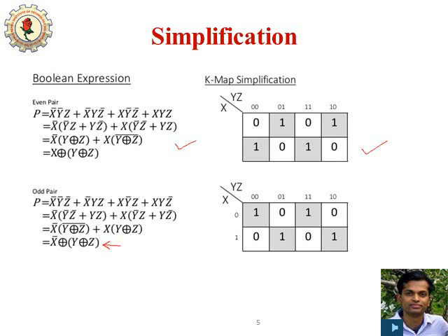So what happens is the right side K-map having the values 1, 1, 1 on the diagonal patterns can be simplified using the left part: P equal to x bar y bar z, then x y z bar, again x y bar z bar, and finally x y z in the bottom left of the first K-map. Okay. So if we simplify it, we get XORing of the three inputs: X XOR Y XOR Z. So that is for even parity.